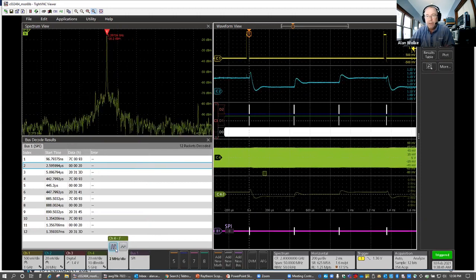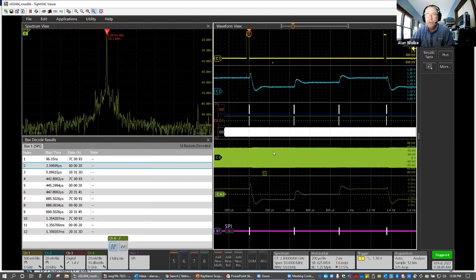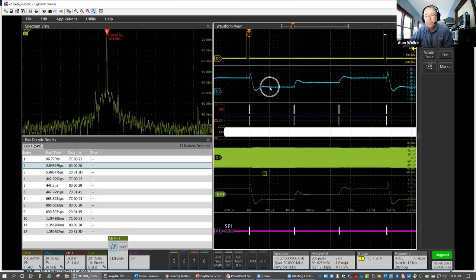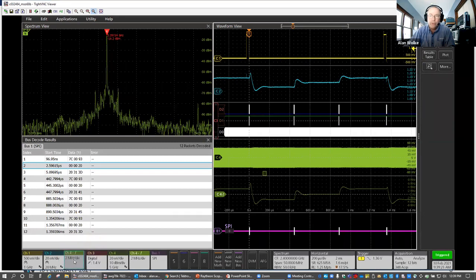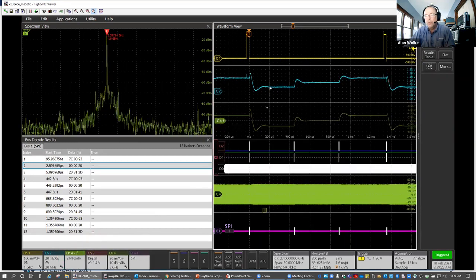This is like that FM demod view of this signal. It's looking at the frequency deviation on the vertical axis with respect to the center frequency. You can see this waveform should, and does, match up with the tune voltage going into the VCO up here on channel 2. You can also make some arrangements of the user interface to make it easier. For example, if I touch and drag that channel 4 badge, I can drag it over and stick it right up next to channel 2, so now I can compare those two very easily.